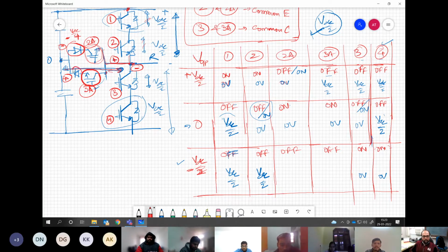So in this middle branch, in the lower half, the diode is blocking the entire voltage of VDC by 2, which means what is the voltage across this device? 0. So whether you keep this device on or off does not matter, because this anyway cannot block any voltage. So simply we can keep it on. There is no problem in that. You understand the point?